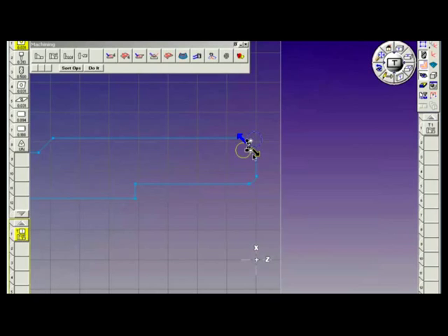I'm going to move my start marker 50 thousandths off the face of the part. But instead of dragging it and guessing where 50 thousandths is, I'm going to right mouse click it, move start point by 0.05, apply it, and watch that white marker snaps 50 thousandths in front of that selected feature.